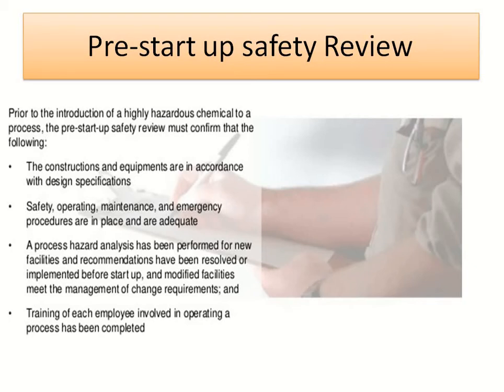The pre-startup safety review must confirm the following: the construction and equipment are in accordance with design specifications; safety, operating, maintenance, and emergency procedures are in place and are adequate; a process hazard analysis has been performed for new facilities and recommendations have been resolved or implemented before startup; modified facilities meet the management of change requirements.